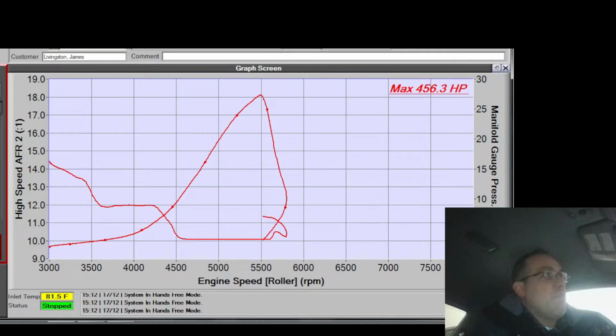So what you are looking for is two main things. One of them is no gigantic AFR transients, and preferably no transients towards the lean position, because lean tip-in often misfires, and you can feel the lean tip-in misfire easily. That's very easy to feel, and it creates a car that doesn't go when you give it throttle, and nobody wants that.